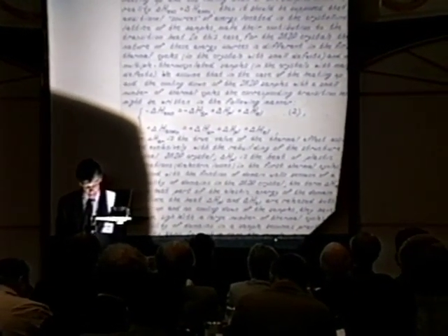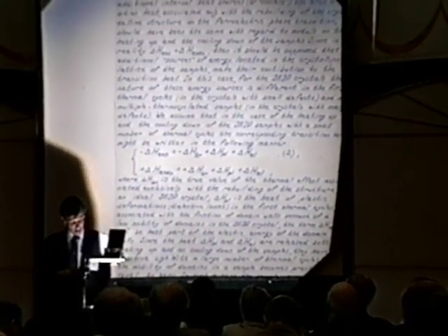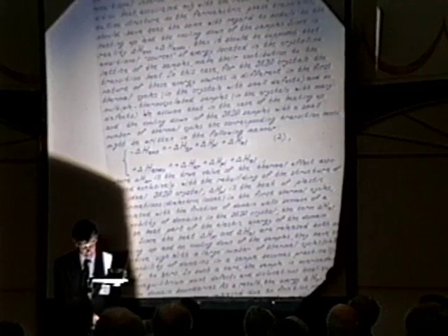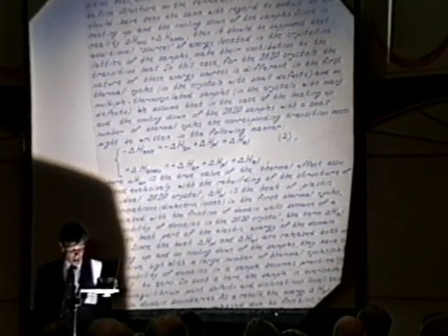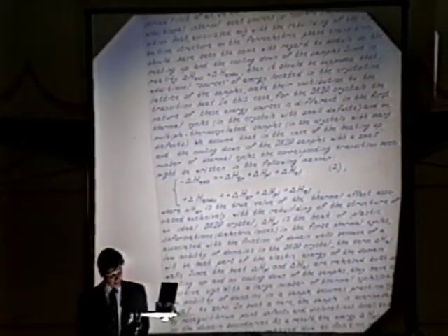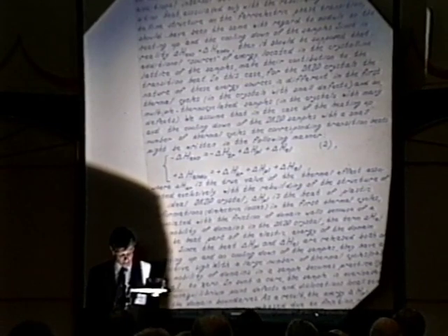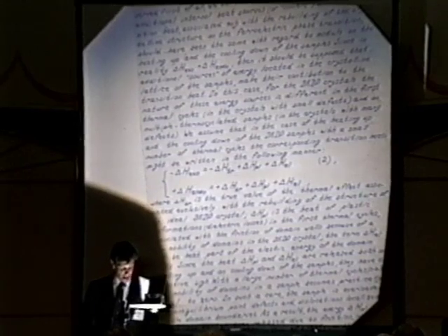The term delta HL will be heat part of elastic energy of domain walls. Since the heat delta HP and delta HL are released both on heating up and cooling down of the samples, they have the positive sign. With a large number of thermal cycles, the mobility of domains in a sample becomes practically equal to zero. In such a case, the sample is overloaded by non-equilibrium point defects and dislocations localized on the domain boundaries.